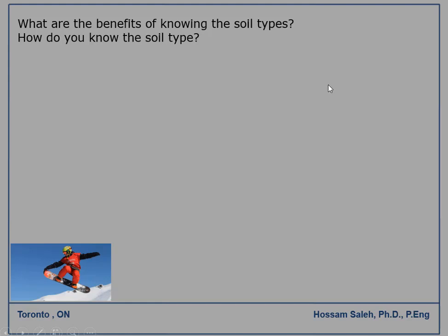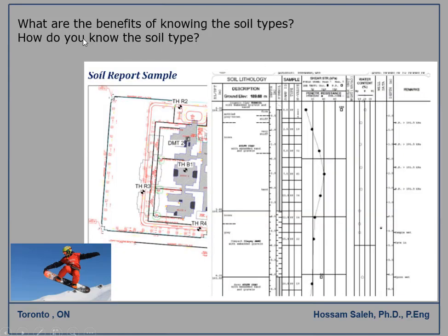How strong is your soil, and what is the type of the soil? You have clay, you have sand, you have silty soil. So what type of soil, and how do we know the soil type? Here in my office, we have a project. I brought you some samples of the soil report. Here is the plan of the building, and here you can see different boreholes throughout the site. A soil engineer or geotechnical engineer carries out boreholes and takes samples from the soil, and when they take these samples, they analyze them, and then they can give us a soil report.